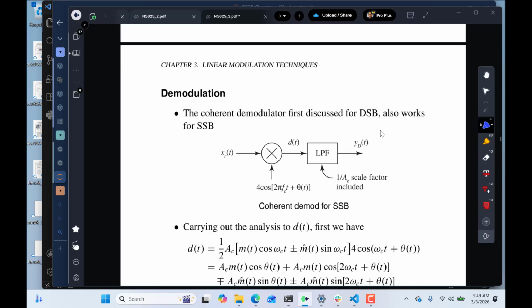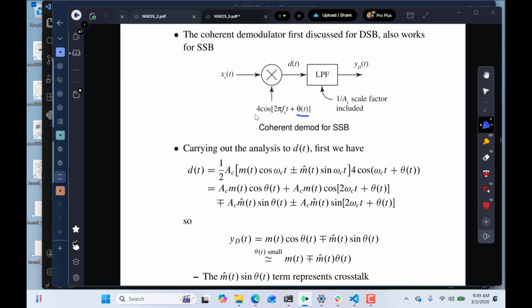So think about how that was set up. Nowadays, we would do different types of multiplexing, and that's what the telephone company moved into, is just switching centers and multiplexing digital waveforms. But in the earlier days, they did multiplex analog. So you can demodulate it, and then here, it's just showing you putting in the possibility of having a not coherent carrier, what happens? You put in a 4 just because we only have one sideband, so the 4 is to make the amplitude come out correct after we take it all the way down through the multiplication and the trig identities.